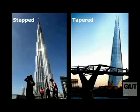And these long-span traffic signal structures would spend all day just going up and down, vibrating at their natural frequency, about 1 hertz. And hardly any wind would cause these things to move more than a diameter. And we're talking about 70 feet, 20-something metres, okay, expand. So they'd spend all day, and of course that motion at 1 hertz for several years generated a lot of fatigue failure. So changing the profile is really important because it destroys this vortex shedding flow.